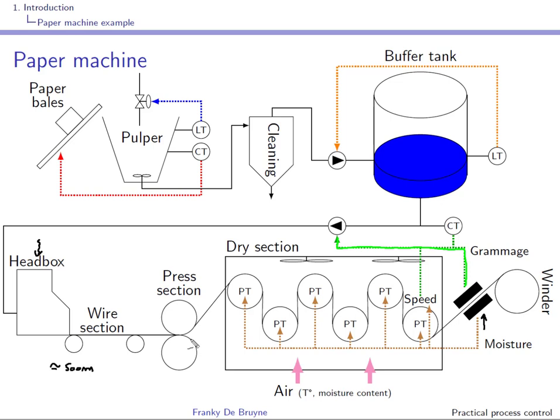This calls for specialized control methods. One option is to use a Smith predictor, and this is covered in section 6, or you can also use an internal model controller, and this is covered in section 7. In this type of control, usually an internal model controller is used.